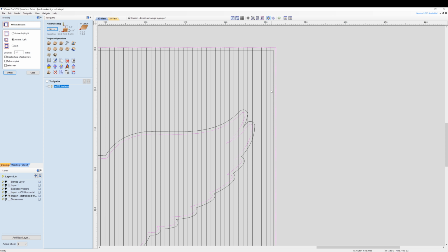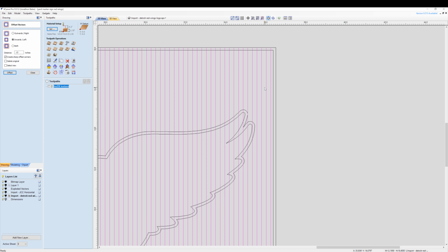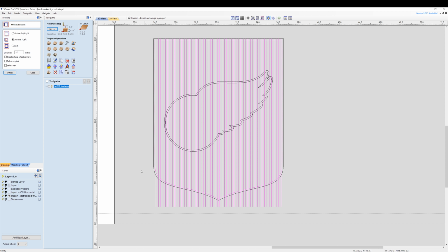So now let's grab this group, and let's grab, holding Shift, this outside perimeter of the offset, right? Just the offset. Now we can press close and go to trim. And what we need to do is we're going to trim the objects on the outside of this boundary. So the first thing is what we're trimming. The second thing is the boundary. And we're going to trim the outside of the boundary. Press clear. It'll remove all of this stuff on the bottom and all these little tabs up at the top.